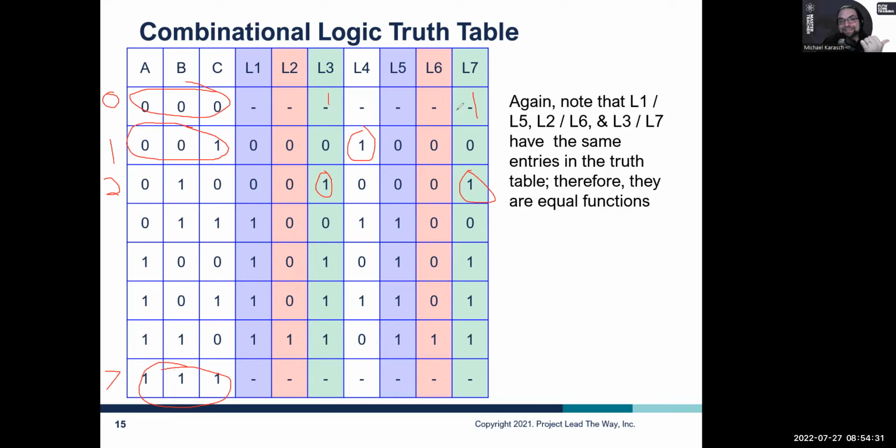Because we designed that last step so it only goes from 1 to 6. It never, ever goes to 0. So I don't need to tell it, turn off all the LEDs when it's at 0. I could. You could. You'll have the skills to design it. You could make it do that, but you don't need to, and it would be extra gates, extra complexity.